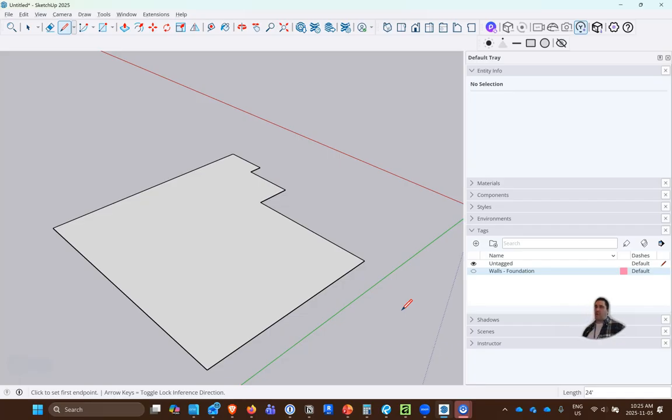And if you remember before, I said our footings were 20 inches by 6 inches. So 20 inches is our width. And just to do some mental math here again, our foundation walls are 8 inches. So 20 inches minus 8 inches is 12 inches, right? I can do math today.